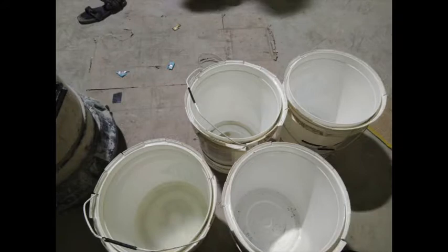The third most important step when you're using the right densifier is the dosage. Now, depending on the manufacturer specification, the dosage varies. But what is important is how do we check the dosage? Usually we use simple tips like planning out an area with respect to a certain quantity of chemical, like in this image, and we ensure that this much chemical is utilized in this area. That has to be predetermined, and again this also ensures how your floors are finally performing.